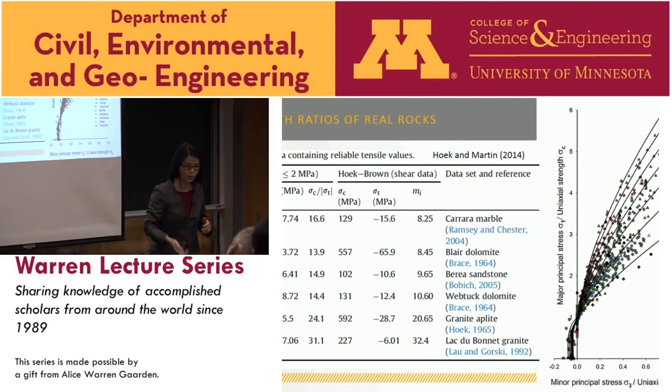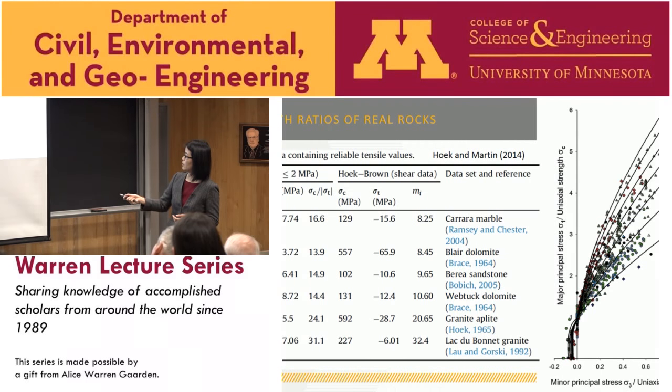And the failure envelope here is very steep, highly nonlinear. Most of the time, people measure only this part, and you fit it with a Mohr-Coulomb failure line, approximated by a linear behavior. But if you extrapolate to the confined extension range, the numerical approach misses it completely.